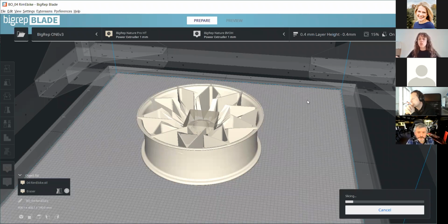So the one thing that you'll notice once I have this preview up is that in order to allow for the difference in infill to happen, it will create a wall in between the two objects. So don't be alarmed by that. It may look a bit strange. It's not actually affecting the exterior of your model at all. It's just creating a wall in between that 15% infill and the 50%. And you'll be able to see this better once the preview's up.